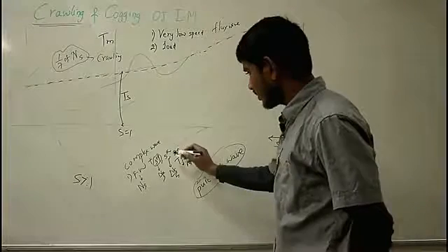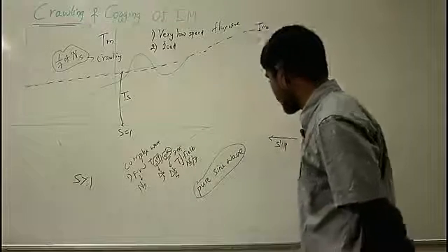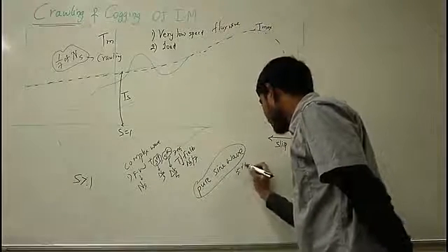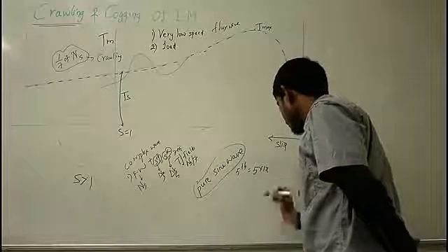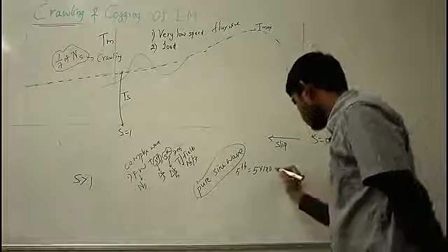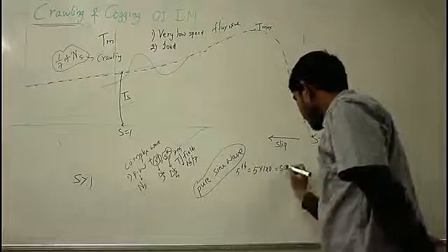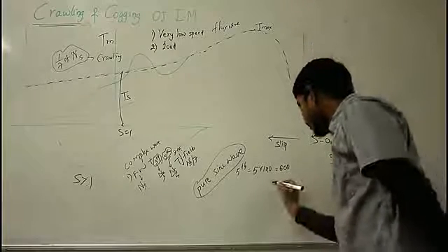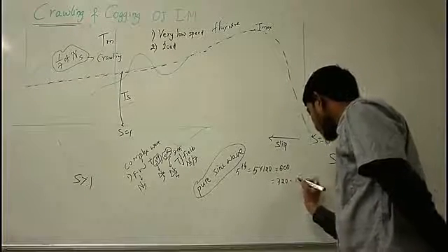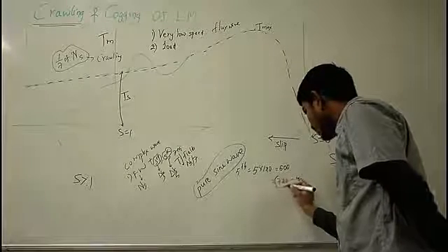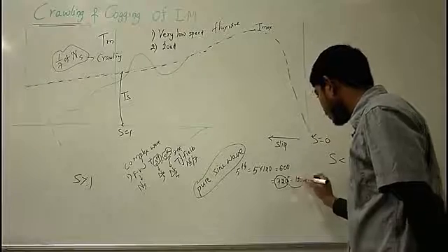Now let us see the fifth harmonic current phase difference. The fifth harmonic is equal to 5 into 120, which gives me 600. If I take 720 as 2 revolutions minus 120, and when you go through 2 revolutions the phase difference is 0, I am left with minus 120.